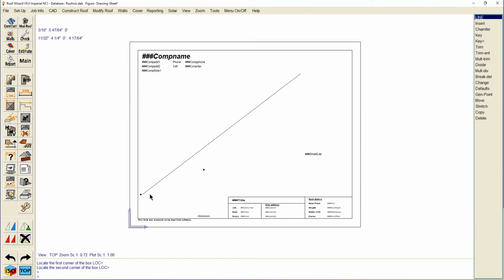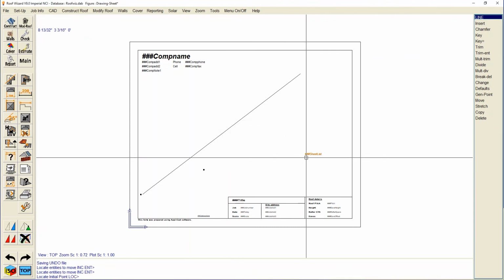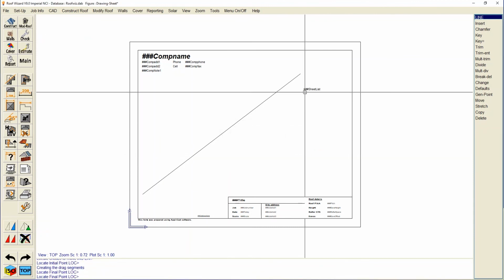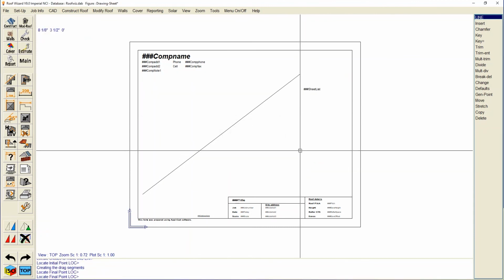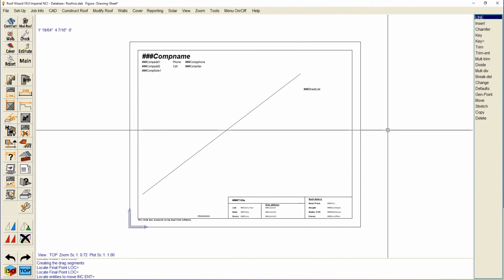So that diagonal line on layer 999 defines the extents of our roof plan, and that's inside the sheet table, so the sheet cutting list will be listed there. Given that we've done that, you might then decide to move that from here back up to there because it's not going to be overwritten by the roof plan, and if I've got a lot of sheets on this drawing, there's heaps of space for the sheets to draw.